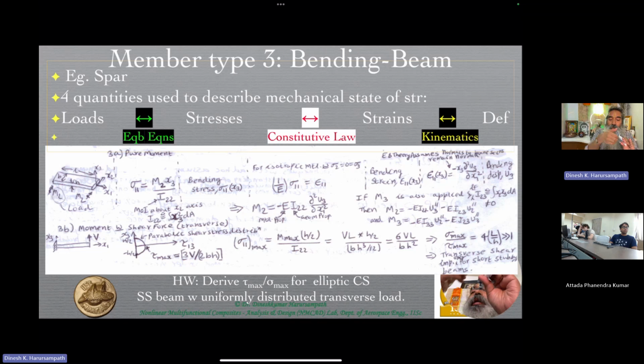On the other hand, the drag distribution and the thrust distribution are all causing the moment about the x3 direction, which is M3, and that is causing U2. Those two will be related to each other in a very analogous fashion, just that the sign convention will be slightly different. Because of the sign convention, instead of a negative, you will get a positive. In fact, on the same slide, I will be talking about that as well.